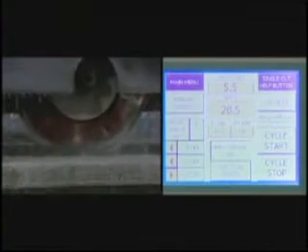Conversely, if the arbor is drawing 6 amps over idle and the blade encounters a hard spot in the stone, the amperage may spike to 7 amps over idle. The amp control will decrease the speed until the amp draw falls back to 6 amps.